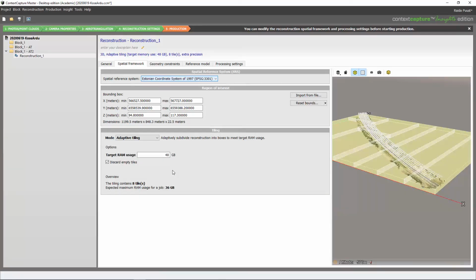In some cases, it is even good to divide your model into pieces, as after each piece is calculated, you can immediately check if it satisfies your expectations. And if not, you can cancel the calculation process and save some time. But it is also clear that if we minimize the number of tiles, the calculation time is also higher for one tile.